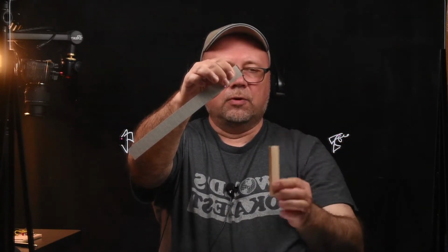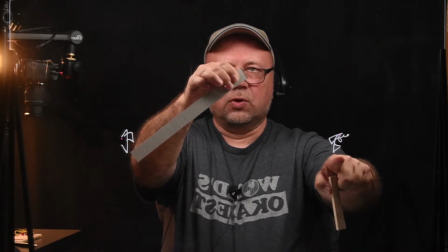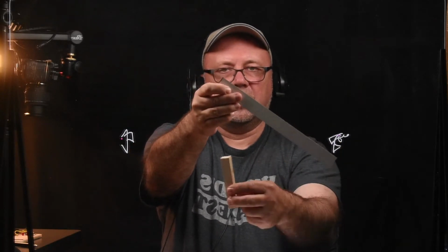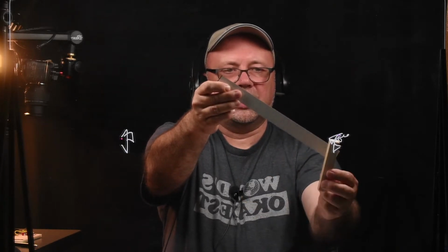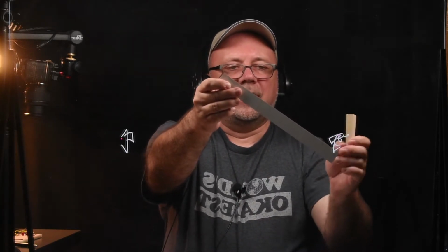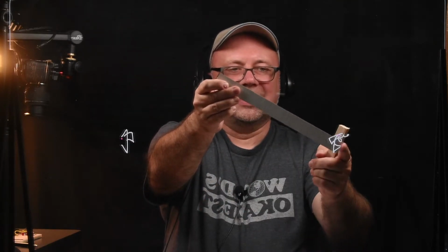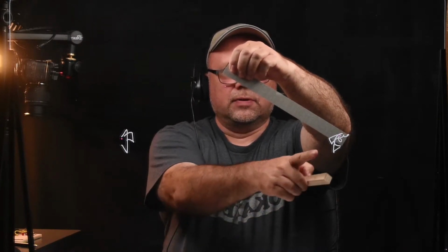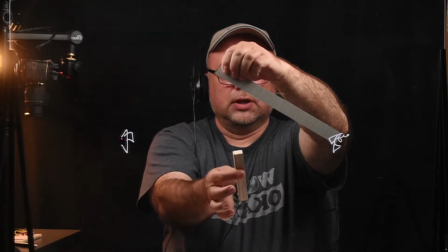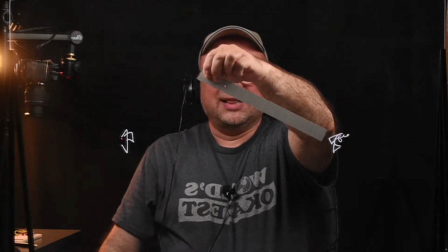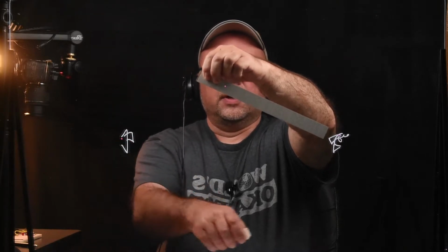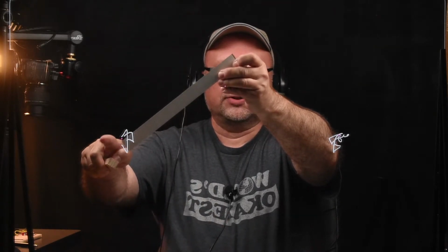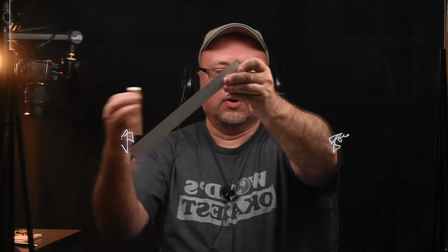So let's say when we bring the magnet to this position, this one becomes logic 1. So we got logic 1 here, this thing moves here, and it doesn't matter how many times we activate this point, how many times we bring it from 0 to 1, this little pendulum device is going to be latched onto this position. Then when we apply the logic 1 here instead, because once we move it that becomes 0, these are both zeros, so that means this is a latched position. Once we apply the logic 1 here, then bang, this thing is going to come here and stay here. It doesn't matter how much we make it 1 or 0, it stays there.